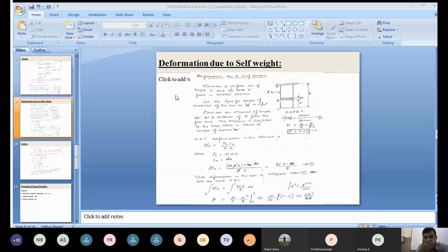Right? Consider an element throughout this length. See, if you consider at this end, is there any weight acting here? At this end, no. As the length increases, the weight also increases, because the whole weight of the volume contained here acts at the CG, right? As the volume increases, weight also increases here.